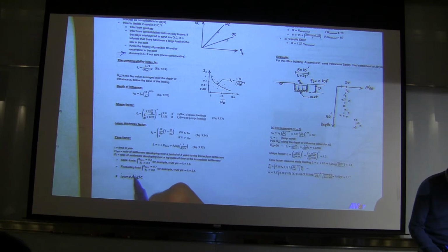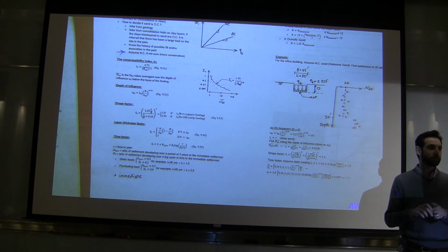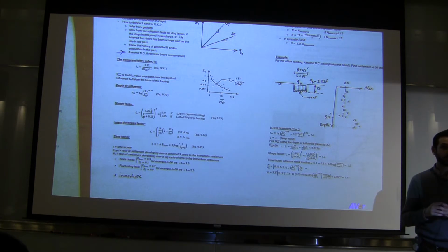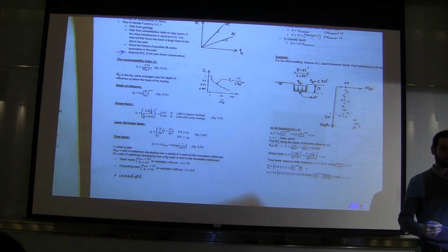If it's a fluctuating loading, those factors are a little higher, because you have a dynamic loading. Can you give an example of a case where we have fluctuating loading? Like a warehouse facility, right? Any mechanical instrument, any foundation that is bearing a load that fluctuates, that is a dynamic load. It could be a foundation for a mechanical instrument. Probably a warehouse foundation is somewhere between static and fluctuating.